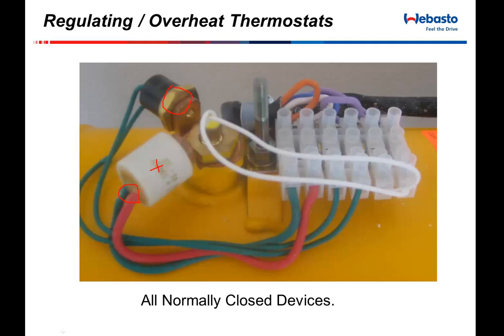The other reason is if you've got it plumbed backwards. Once you start the engine, the engine coolant flow and the Webasto coolant flow are kind of fighting each other, and it takes out any flow through the unit, which can again overheat it. If the driver complaint is that the Webasto works fine in the morning, but when I start my bus I have no heat, what's happening is you don't have any kind of coolant flow because the two systems are both deadheading right up against each other. Again, it will create a situation where you can overheat the unit.